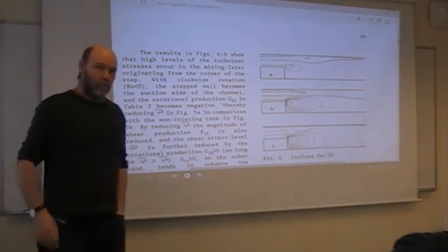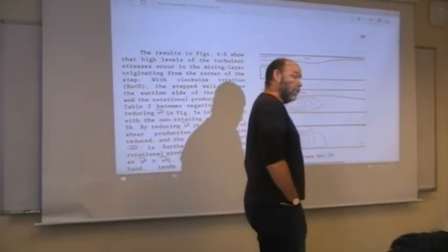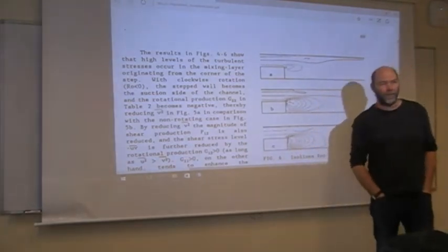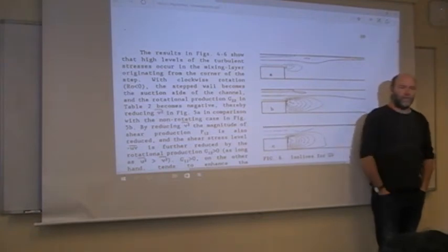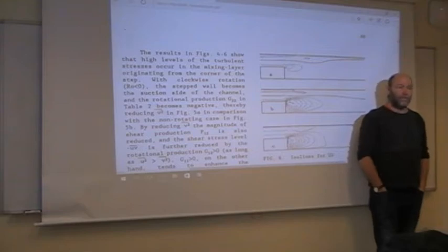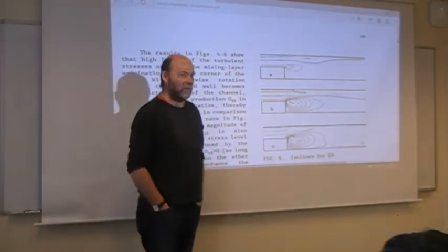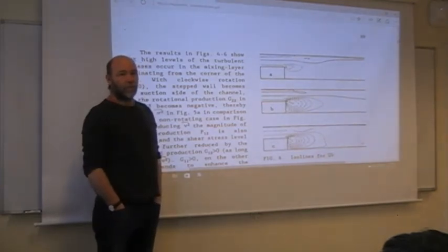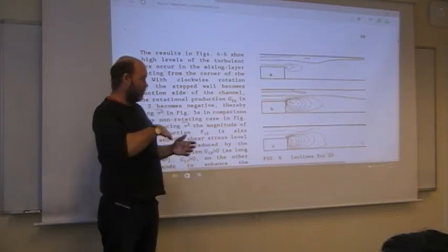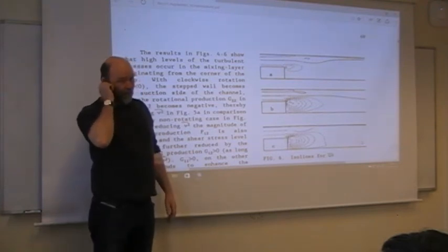But you said that we can use the K-epsilon model if there is no rotation? If there's no rotation, sure. Don't expect very good results though, because it has problems with the backward-facing step. It's a classical test case for K-epsilon, and normally it will fail very badly. You can get any reattachment length you like by changing the mesh, so it's a very bad idea. K-omega would be much better actually. It treats the walls better, it's better with recirculating flows, and it can handle adverse pressure gradients better.